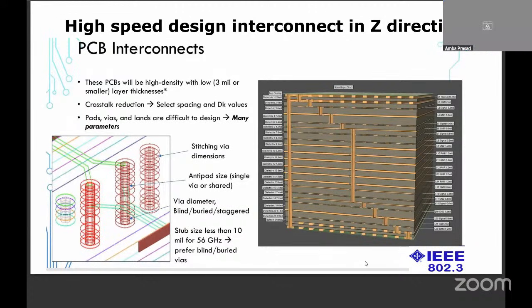So unless we are exposed to very high-end EDA software in simulation, most of the layout designers will see via only in X and Y direction. They won't see the vertical direction. So that puts capacitive and inductive parasitics. This has to be properly modeled. Very high-end CAD packages are able to do this. So this issue more or less is resolved, but again, it has to be resolved.